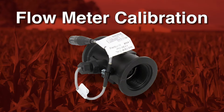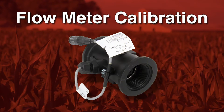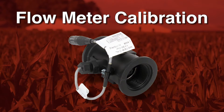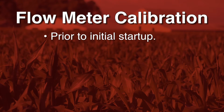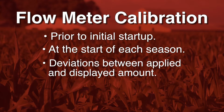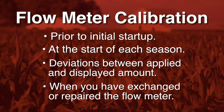The last step in the configuration process is to calibrate the flow meter. The flow meter is used to measure the amount of applied ammonia. Because the number of pulses per gallon can change during the lifespan of a flow meter, calibration must be carried out in the following cases: prior to initial setup, at the start of each season, if you notice there are deviations between the actual applied amount and the displayed amount, when you have exchanged or repaired the flow meter.